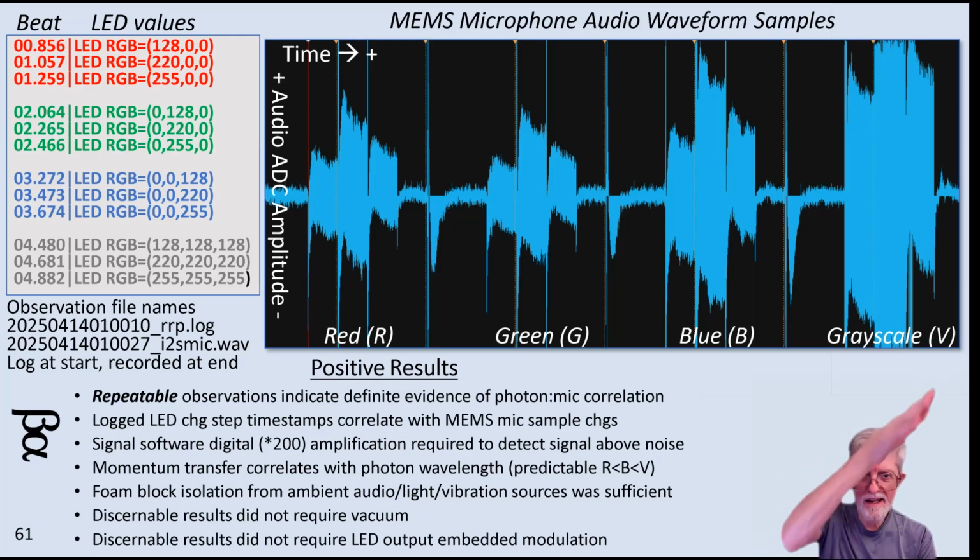And I can explain why it kind of diagonally notches off. You would think it'd be flat, but it diagonally notches off. And there's an explanation for that. And the vertical long blue lines, those are known as spikes or ring, and that's in the actual voltage levels of the LEDs. You don't see that when the light changes, like when you tell an LED to turn on. The spike is such a short duration, you don't notice that the LED gets really bright for a very, very brief period of time before the light level stabilizes out.